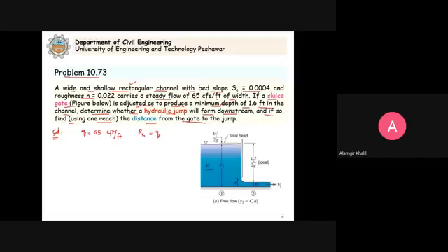When we consider the hydraulic radius as equal to the depth of flow, the trial and error solution is avoided, because the hydraulic radius is flow area divided by wetted perimeter, so the depth of flow is present in the numerator and the denominator. With this wide and shallow assumption, the hydraulic radius is equal to y, and we can get a direct solution.